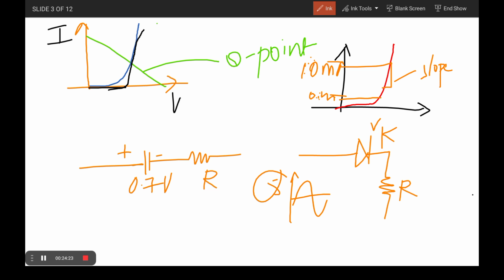So for that purpose, in order to maintain the same relation, first of all you have to set the p-n junction diode in DC bias, and later apply the AC voltage. First you have to put the diode at the quiescent point, the Q point or operating region.